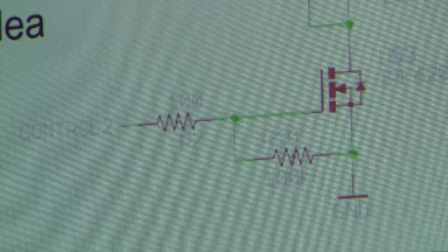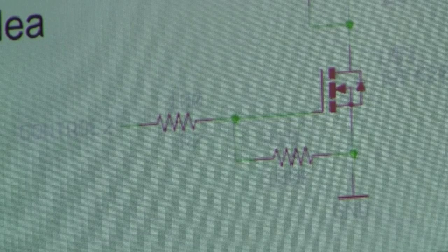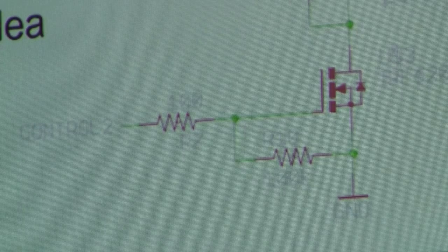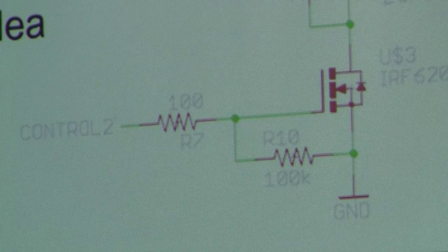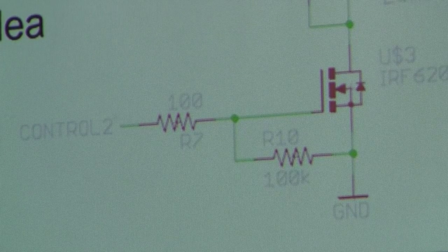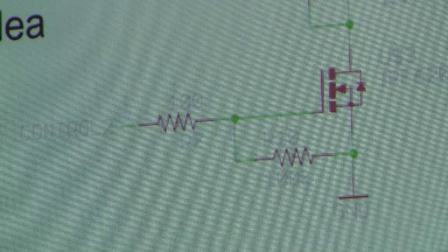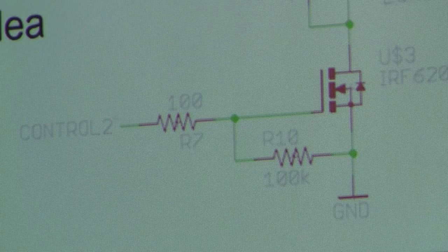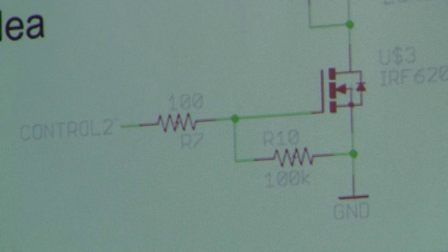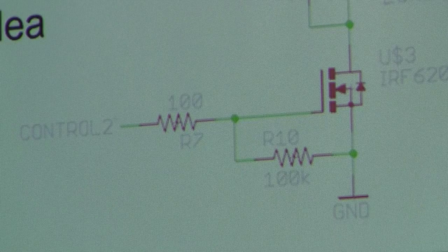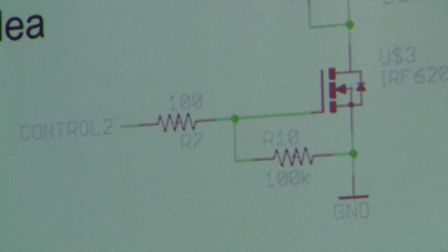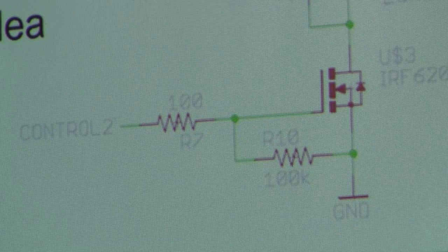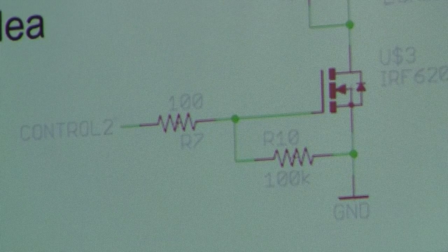The reason you have that gate pull down is that capacitance collects voltage. So stray voltage could accumulate on that gate until it turned on and randomly turn on your relay or whatever it is. How'd you pick 100K as a value? That's a reasonably aggressive value. You'll see anything from 100K to a meg to 2 meg. The really high ones are generally used when you're using a really weak driver. And you really just need something to keep static from being able to pull it down.